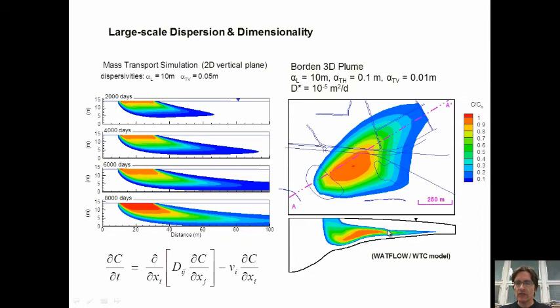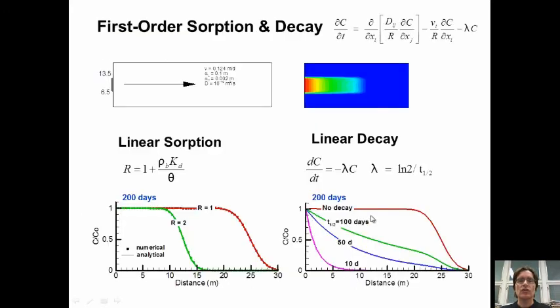You want to see this in the vertical sections here, getting good resolution of these gradients. The plume is well defined. It's not being spread out vertically. It's following the base of the aquifer very well, following the flow system very well. So these are the kind of characteristics you want to look for in a simulation. Make sure there are no boundary effects. Make sure your dispersion is controlled, that you're not getting numerical dispersion or oscillations. So those were cases for non-reactive contaminants.